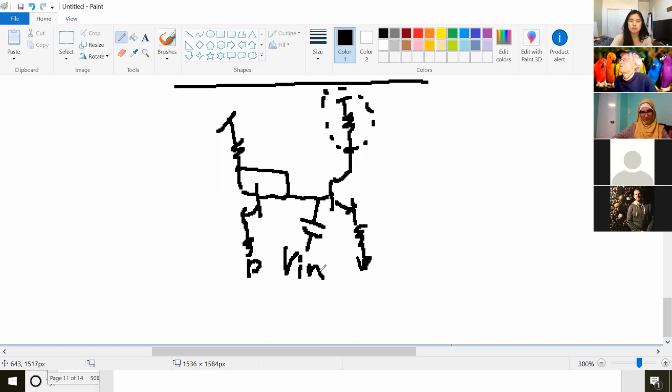what's that capacitor do? Is it a low pass filter or a high pass filter? Does it let high frequency signals through or low frequency signals through? Low frequency. What's the other end? High frequencies. Yeah, it's confusing because it looks like it should filter out high frequency stuff, but remember that the voltage across a capacitor can't change instantaneously.